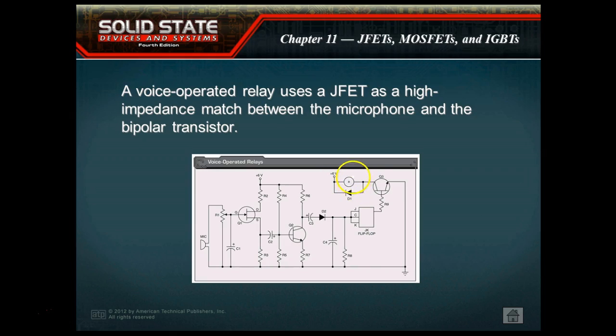Of course, we talked about this. This is a relay up here, and we talked about the little counter EMF we get off of the relay. And you're going to have to remember this even if you take PLCs, and when you start running relays with transistor output PLCs, you're going to have to put those counter EMF diodes down there. And guys, I wish I could remember what I was going to say.